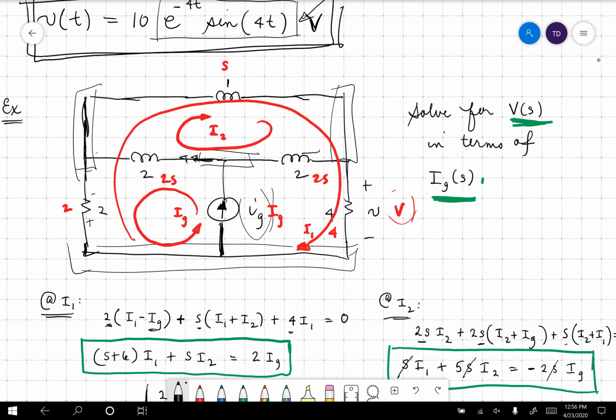So we know IG is the current. Whatever current goes through here, we know the amount of current through here. Let's just call it IX, and call this one IY. Well, we know that IX is equal to IG minus IY. Obviously, it depends upon the source, but in terms of other things in the circuit, it only has to do with this current over here. Then, if we looked at the voltage across all of this, from here to here, that's the voltage across this one up here. So there's dual dependency. These inductors have a dependency upon each other just by the way they were put in the circuit.